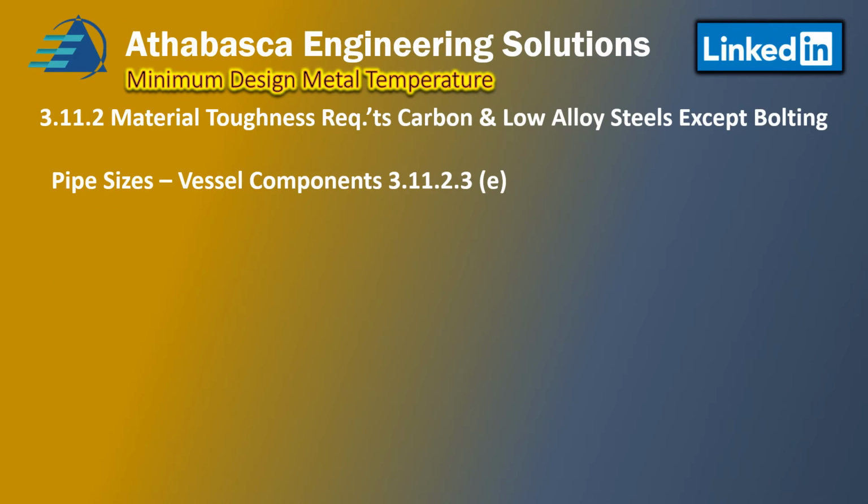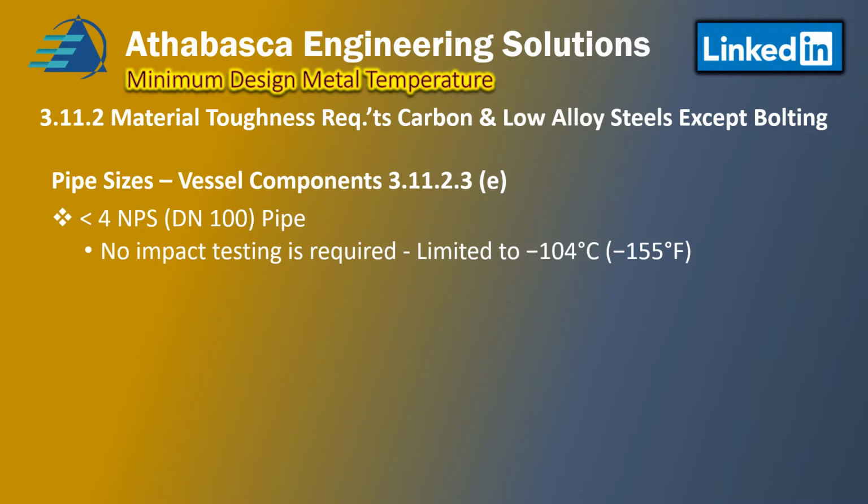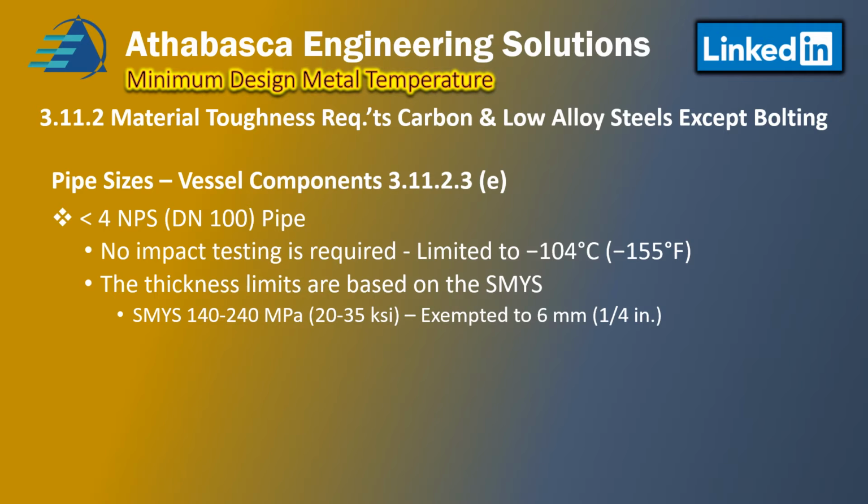So let's go to pipe sizes of vessel components, 3.11.2.3E. If we're less than 4-inch in pipe size, then no impact testing is required, but that's limited to minus 104 degrees centigrade, which is minus 155. So that's the lower limit, excuse me. And the thickness limits are based upon the yield strength of the material.